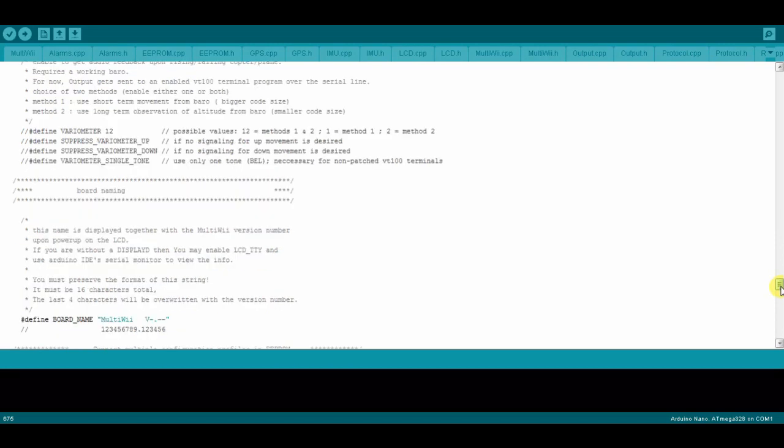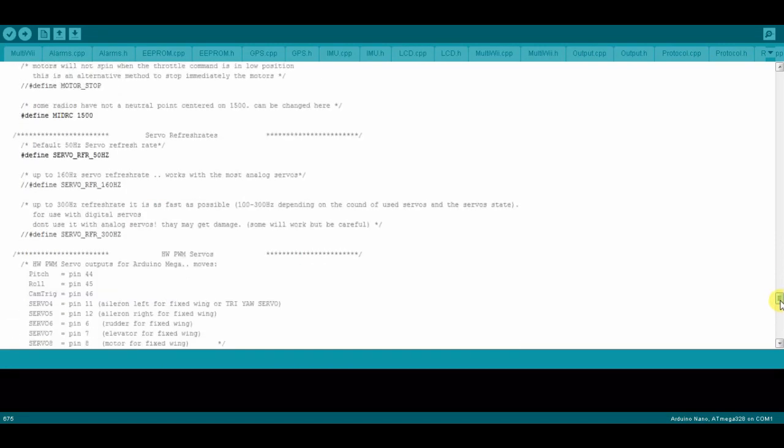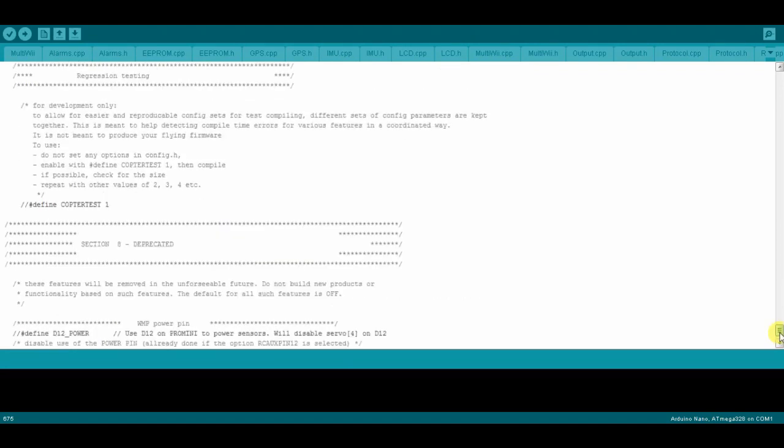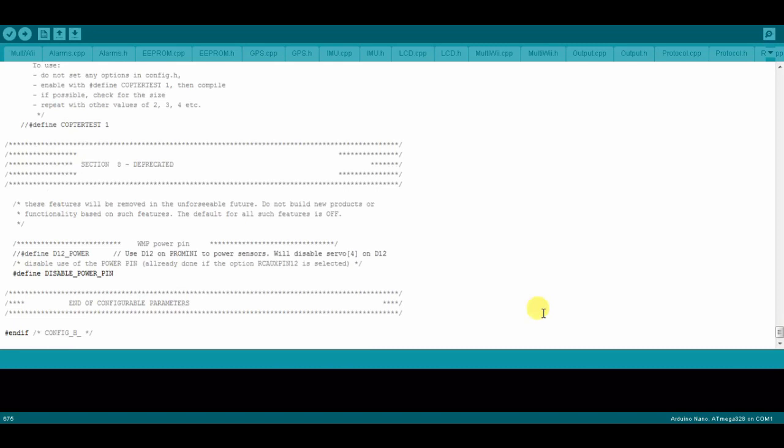Right afterwards you go into their MultiWii software, and there you can really play with the MultiWii SE board specifically, or activate different altitude holds, create different waypoints. If you want to go into mapping, kind of like what I'm trying to do right now, you can set that up, and your drone will already have a predefined flight path and everything. So basically that is it, guys.